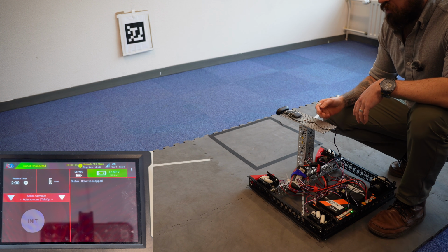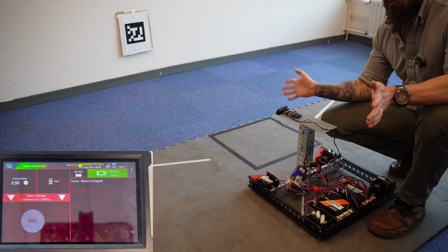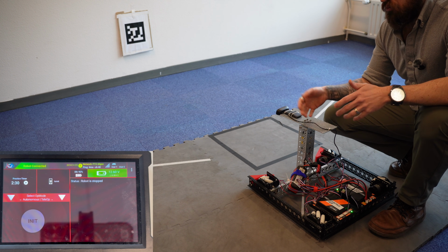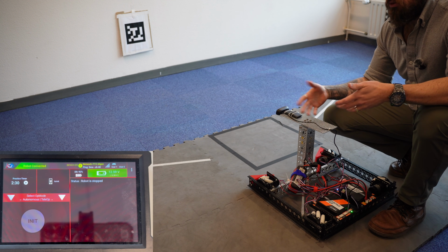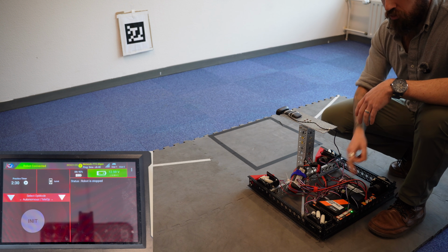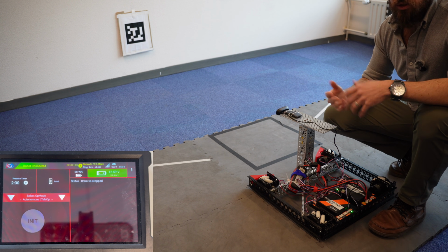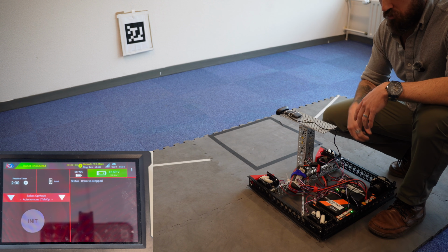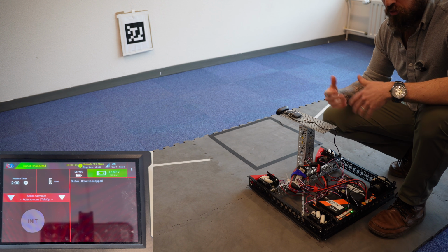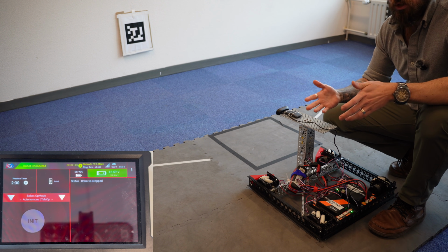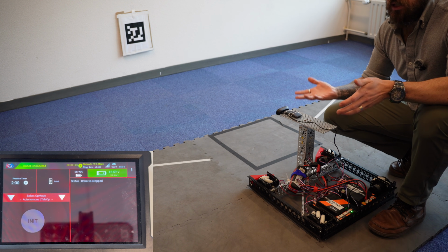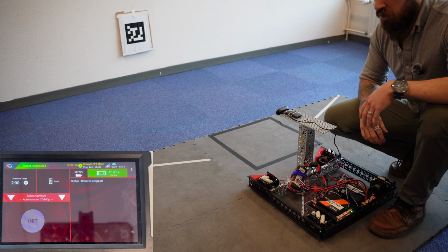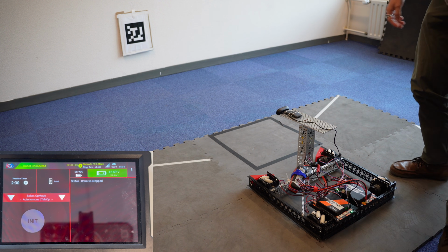This does work a little more reliably with a camera that has a much wider field of view. I actually can't rotate super fast with this, simply because the time it takes for the AprilTag to process on board on the Control Hub slows down my loop time, so I can't get this going really quick. Whereas if you were to have some offboarding, something like a Limelight camera with much higher FPS than the C270 is set up for, you'd likely have more success with the speed of your rotation. So keep that in mind in this tutorial.